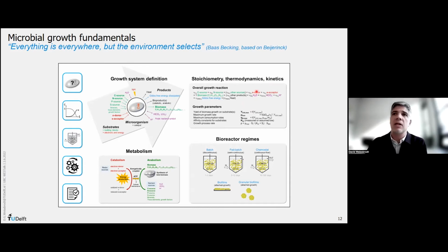So kinetics would relate to the volume of your reactor. How fast the reaction goes will tell how big or how small your tank should be. With stoichiometry, you know what are the ratios of materials that are needed to produce the biomass or to produce your polymer that you want to valorize. We don't need to have all these sequencing technologies to design processes. Process design goes via stoichiometry and kinetics, and it is assisted by mathematical modeling.